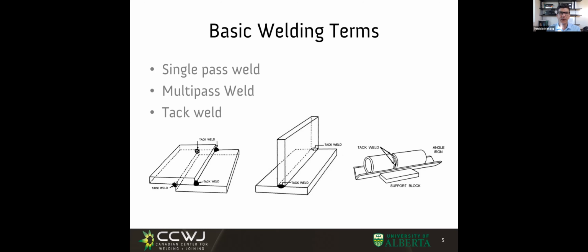But guess what? If I have a multi-pass weld, the first pass might be a little bit dirty, but the second pass is fairly clean because it's on top of my previous weld. It didn't get to oxidize or get dirty somehow. And so some electrodes are good for single pass welding. Some electrodes are for multi-pass welding. Isn't this interesting, right?